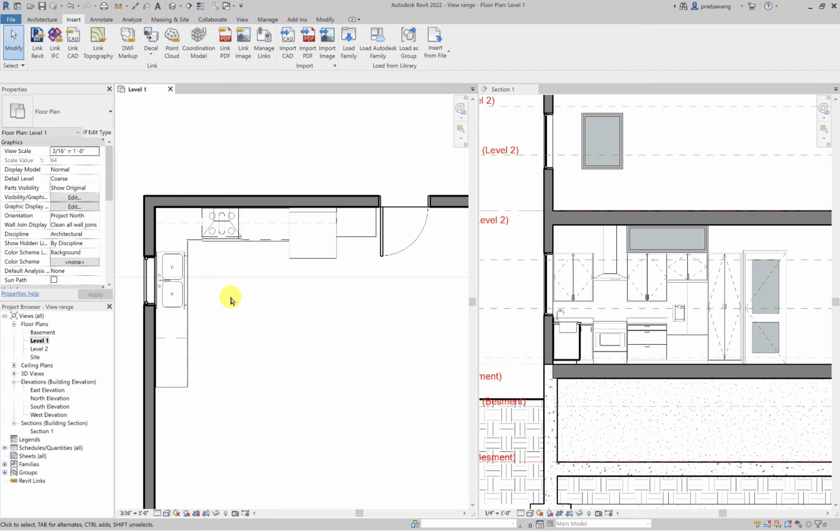In conclusion, for any elements that belong to the 3 categories that I mentioned earlier, if you need them to appear in plan view, you need to make sure that they exist between the top plane and the cut plane. They can overlap with the top plane, but they cannot be completely above the top plane.